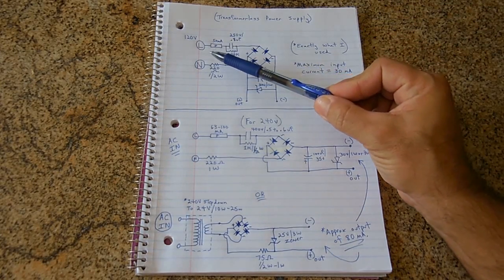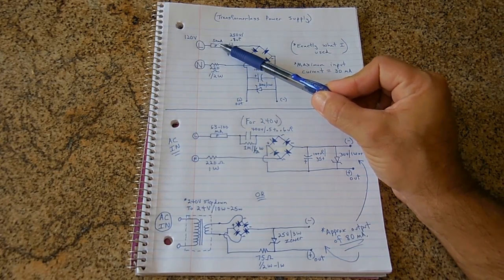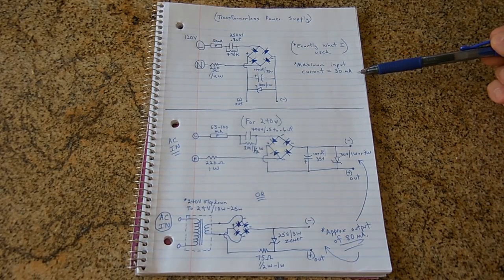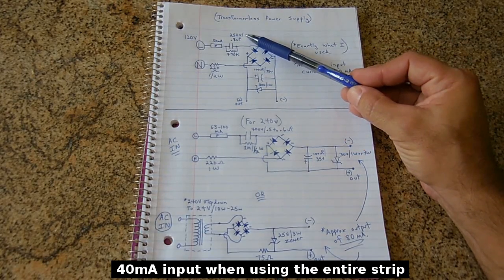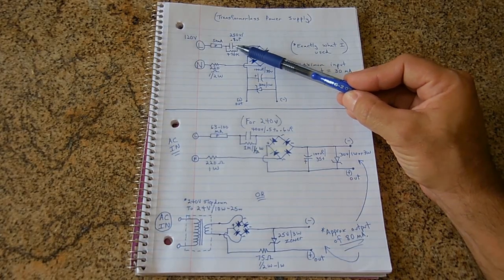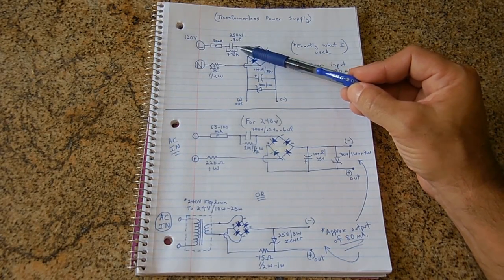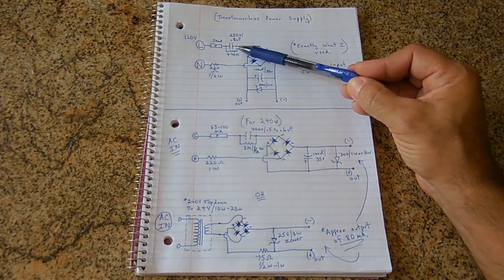Here you have your 120 volt line. This right here is a 50 milliamp fuse. Try and keep this under 100 milliamps because the amount of current that flows into this circuit is very low. It's around 30 milliamps. So keep that well under 100. You're going to need a 250 volt non-polar 0.8 microfarad capacitor. Now type X is preferred, but if you only have poly capacitors, they'll also work well. Be sure to have this 470K quarter watt bleed resistor in parallel with that capacitor.